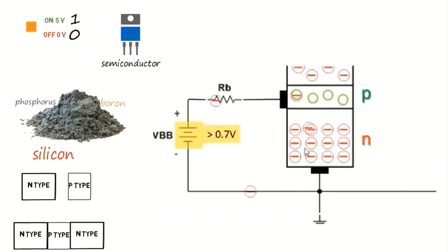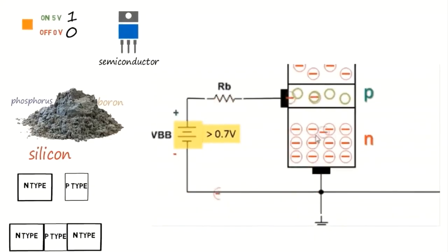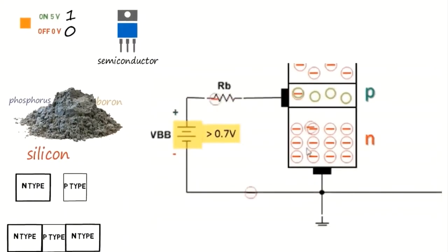In a typical NPN transistor, due to certain phenomena at the PN interface, a special region called a PN junction forms between emitter and base. It only conducts electricity when a voltage exceeding a certain threshold is applied. Otherwise, it remains switched off. In this way, small variations in input voltage can be used to quickly switch between high and low output currents.